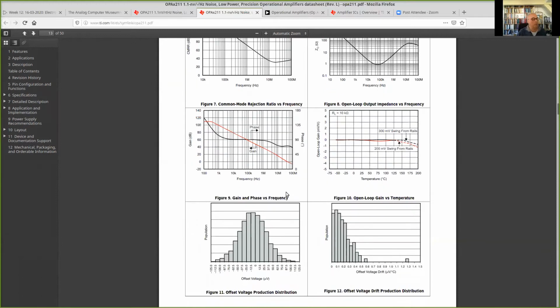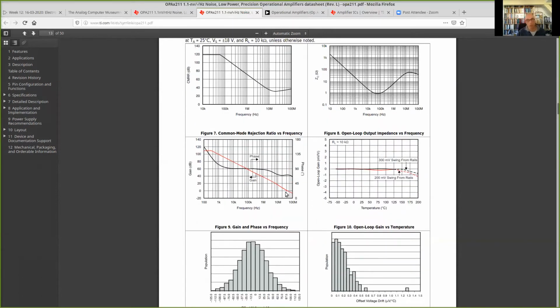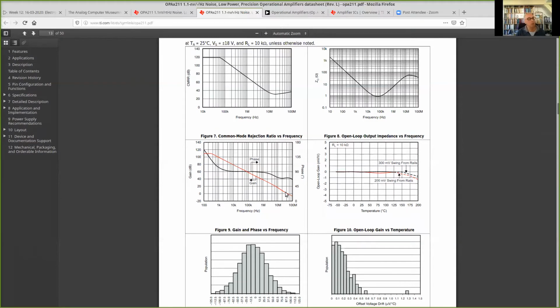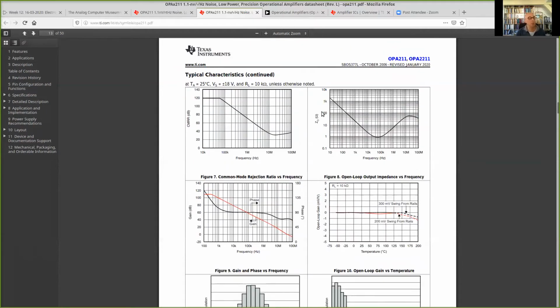And we can try to estimate this from this figure. And that's why we did all these exercises to find the relation between the pole-zero diagram and the magnitude and phase plot of a transfer function. So let's try to do this. And here we have the output impedance. That's seldom specified. But now you see, they plotted from 10 hertz. It appears to be like this. But where does it stop?